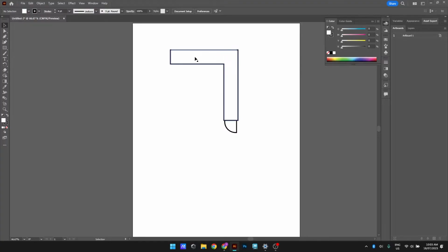Some furniture inside. I'm going to use the rectangle tool again. And same as last time, just click once. So I want a bench that runs down the middle of this, and I'm going to make that bench 8 meters long. And I'm going to make it, the height is actually the width here, 0.5, so that is half a meter wide. So half a meter wide, 8 meters long, which I can place in there.